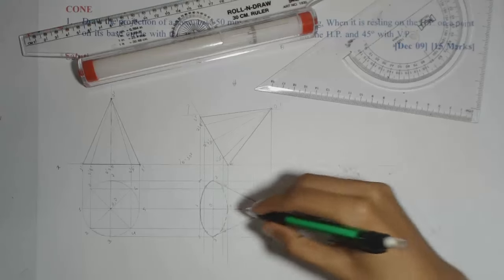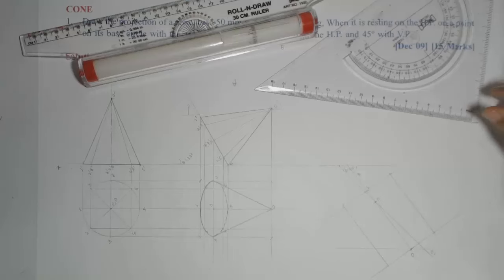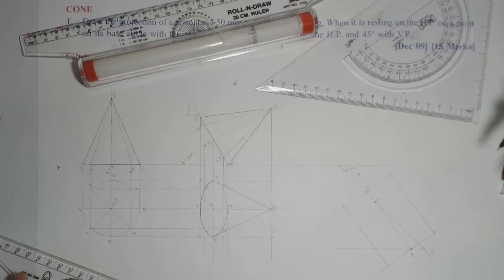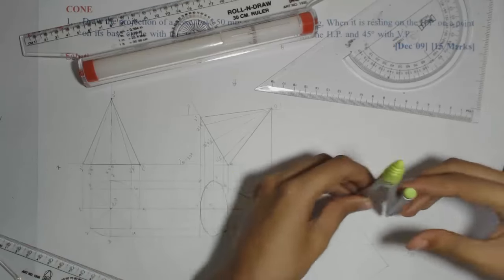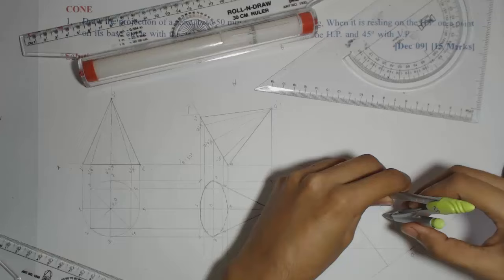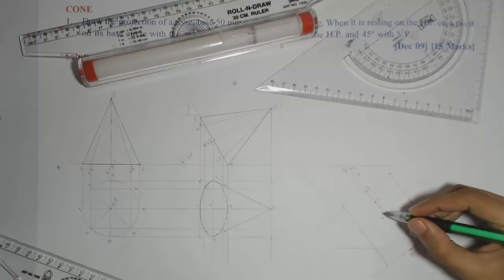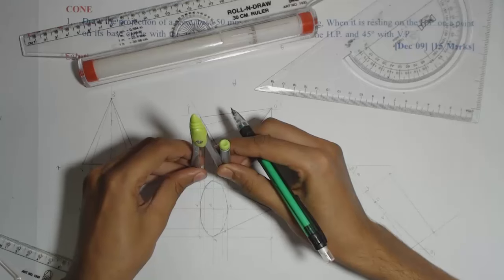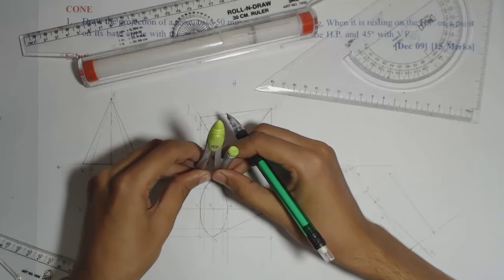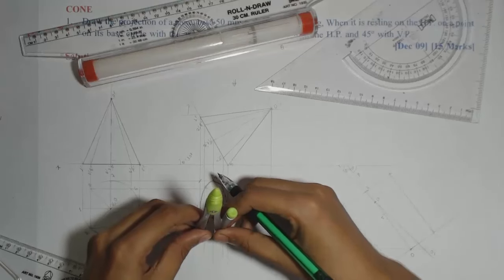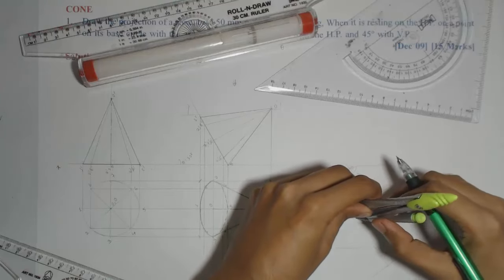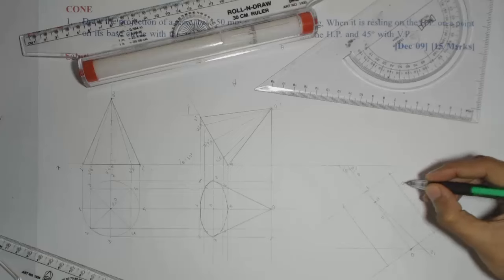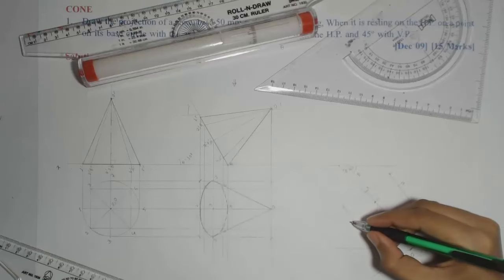Now we'll draw this ellipse and the tangents in that. So after doing this, now we'll mark 1 to 5 on the same line, center line. So here I'll get 5. Then for 3 and 7, we can take the distance from this corner, which are lying again on the boundary, 3 and 7. So from both the corners, I'll mark. So this will be 7 because we are tilting like this, and this will be 3.